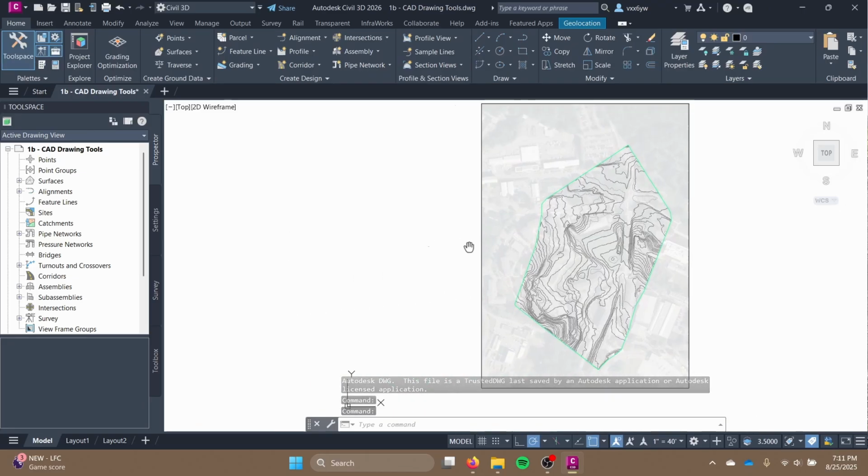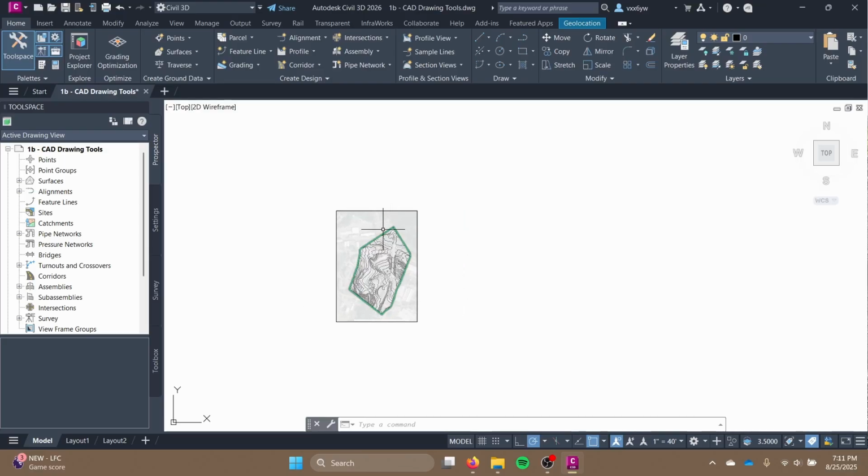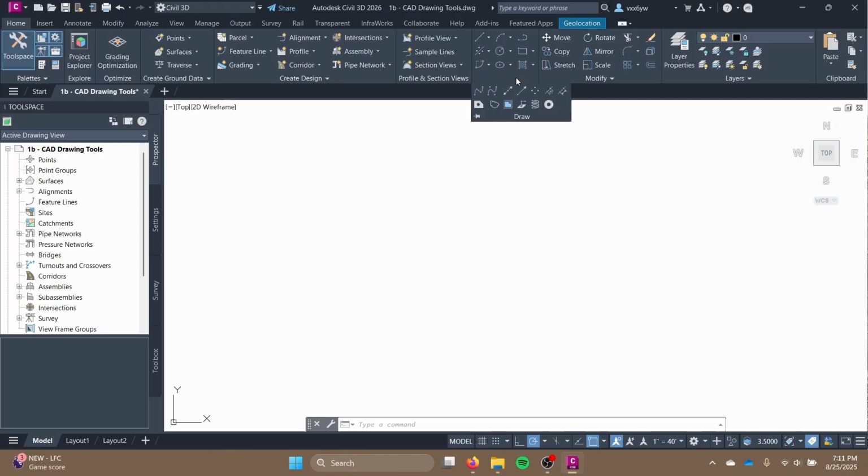All right, now that we've done that, we're just gonna go off here into the side of our workspace where the majority of our work will be on this surface or near the surface here. So we'll just go over here a bit of the ways away and talk about the drawing tools. Your main drawing tools are located on the Home tab of the ribbon under the Draw and Modify sections. If you click on the drop downs, you can actually see that there are more tools available than what is just shown, but you'll rarely be diving into these. You can also access pretty much every single command through the command line where you just type.